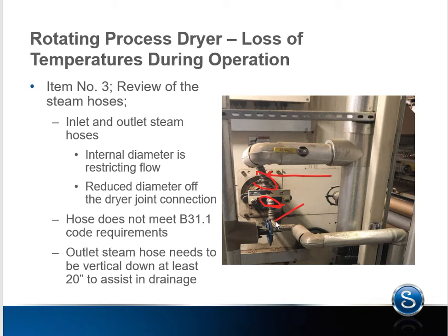The other thing is that coming off a rotating dryer, we want to drop down further to assist in the evacuation of the rotating dryer, because condensate gets processed by gravity. Here we're defying gravity. We're coming through the center part of the rotating dryer.